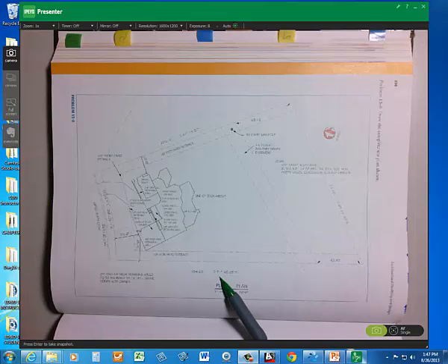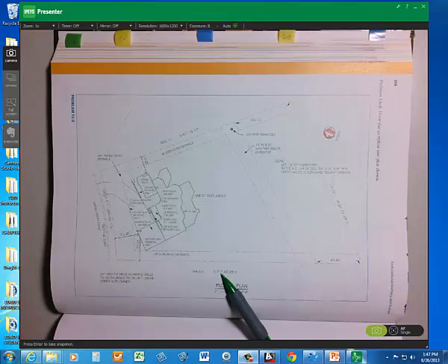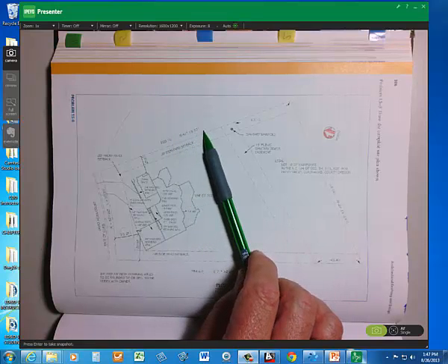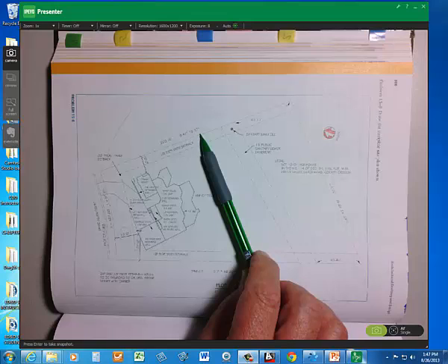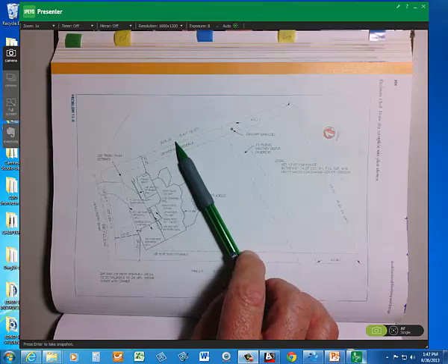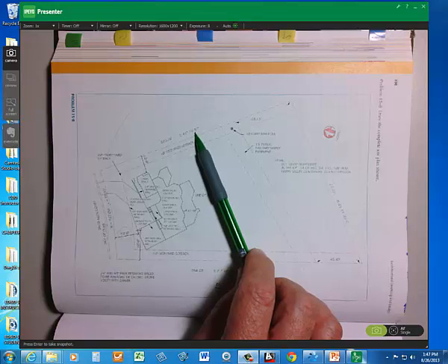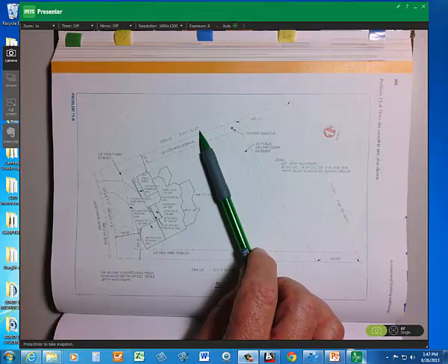Also, the degree measurement, the bearing, would be more accurate on the other sheet, on 15-9. So you use that. When you lay out these bearing lines on your CAD screen, use the south 41 degrees, 15 minutes, 57 seconds.